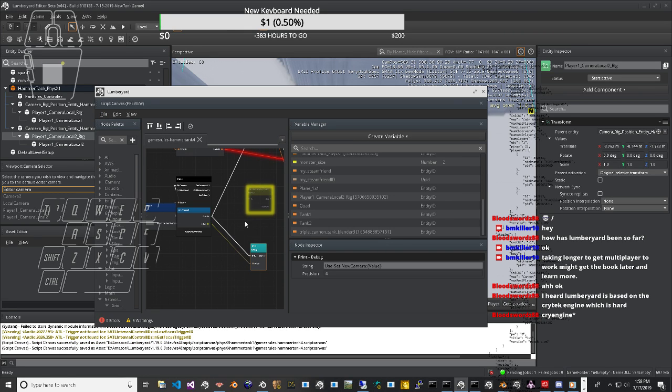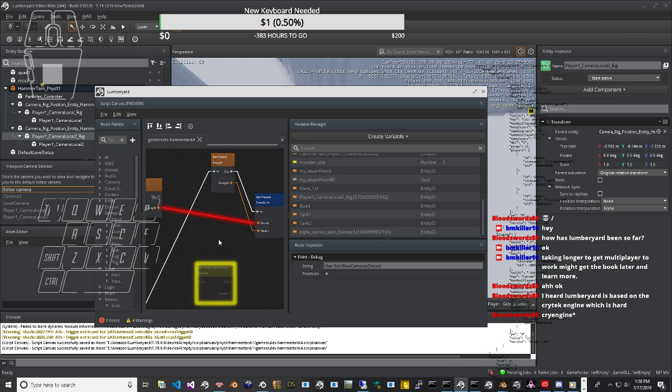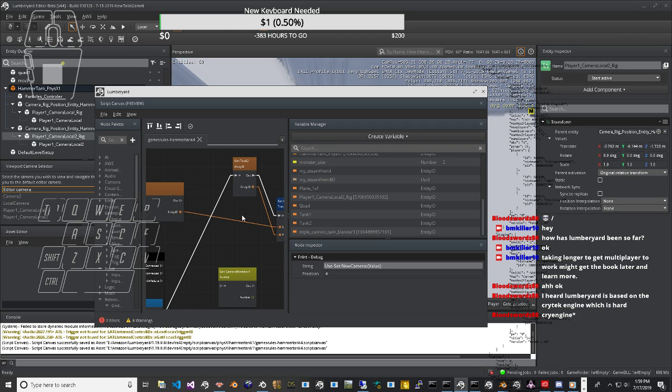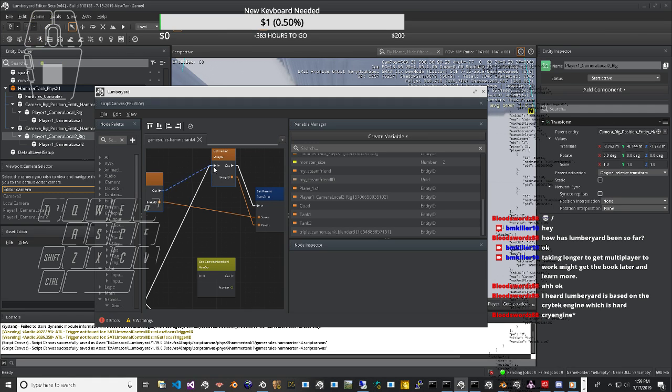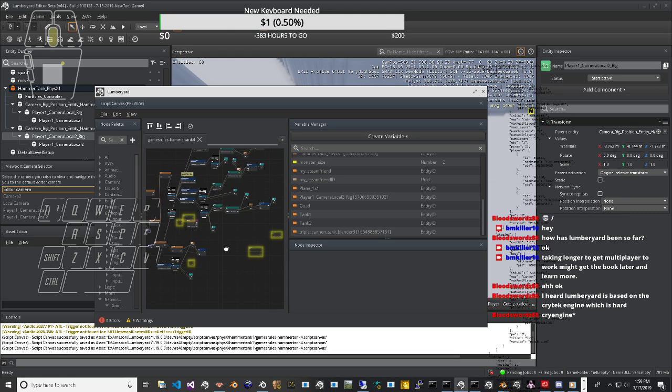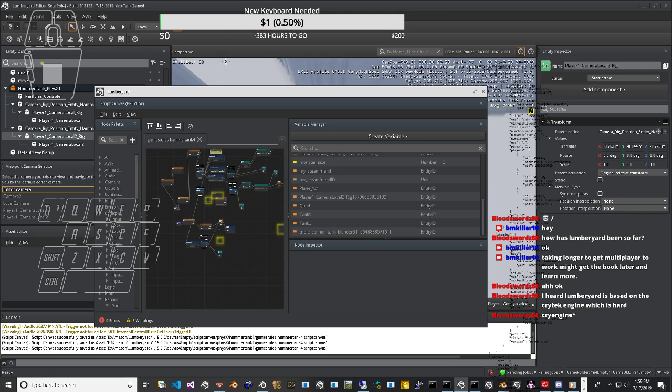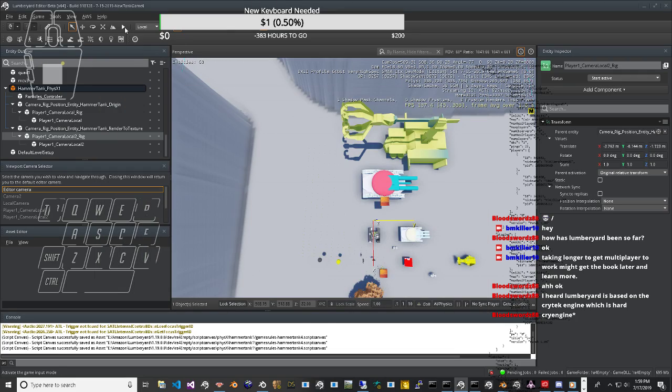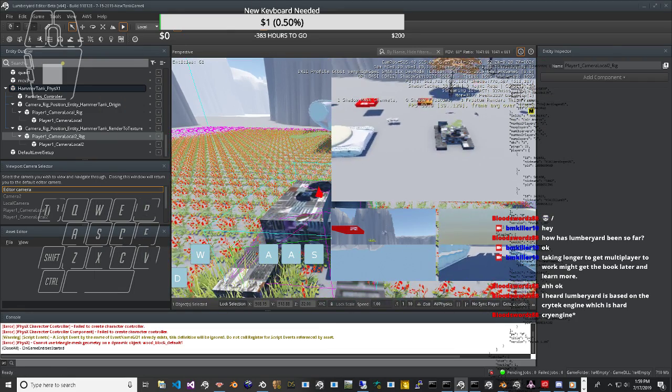Now, imagine the x-axis of car projected on the xy plane of each wheel frame and translated without changing its direction to the origin of wheel. The angle of wheel's x-axis, which is the same as the plane containing the wheel, to the projection of car's x-axis, defines the steering angle of that wheel. Finally, imagine path's x-axis projected onto the xy plane of wheel in exactly the same way. Its angle to the x-axis of wheel, in all generality, defines the slip angle.